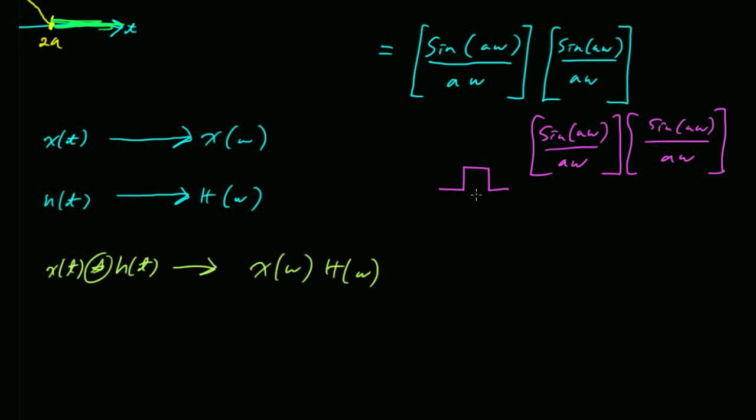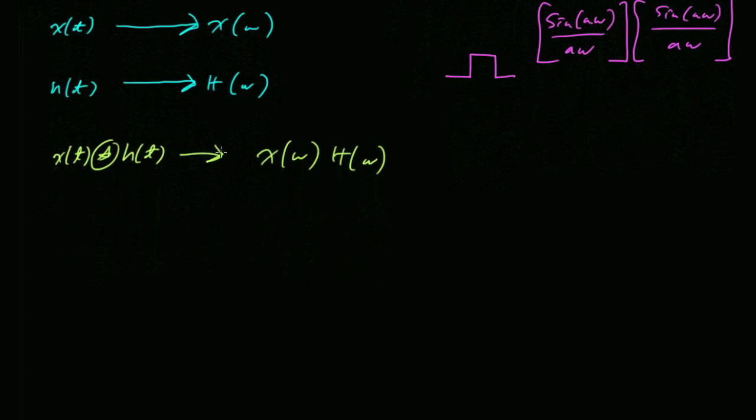It's not okay that this works. All right? But it works. So just another example of convolution in the time domain corresponding to multiplication in the frequency domain. And as we learned on Monday, it works the other way around. If you take two signals and multiply them in the time domain, what happens in the frequency domain? You convolve.